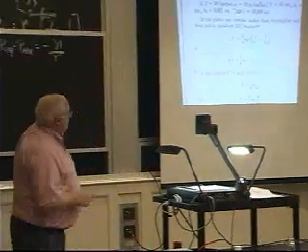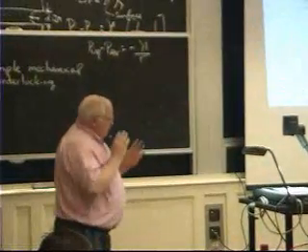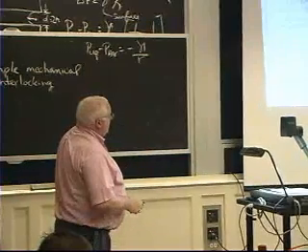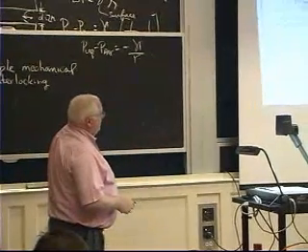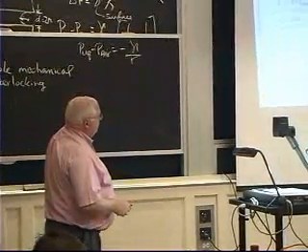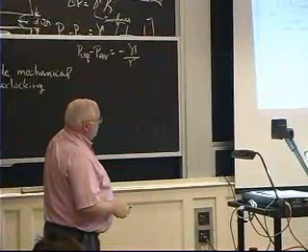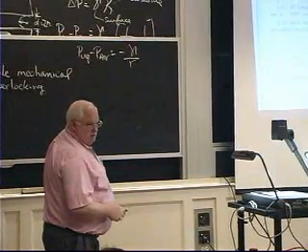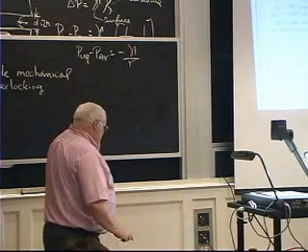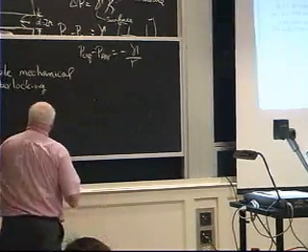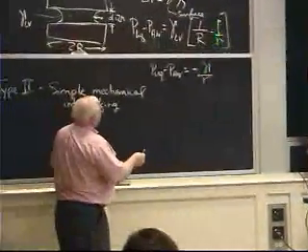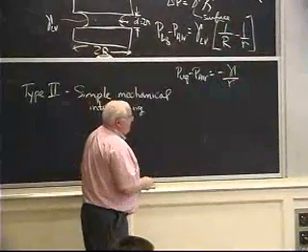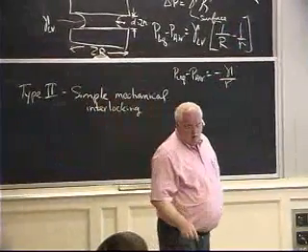But the important thing about this equation, the force that you're squeezing things together and the time is dependent, mostly, this is just geometry, 3/4 pi a to the 4th, viscosity and the final joint thickness. So the strength of this joint goes as 1 over the final joint thickness, okay? So the thinner the joint, the stronger it's going to be.